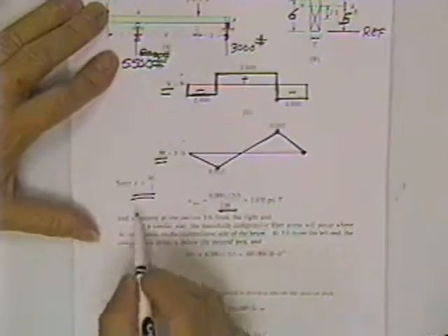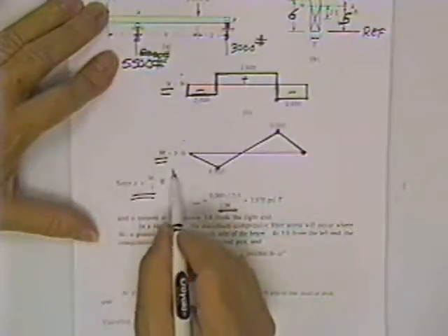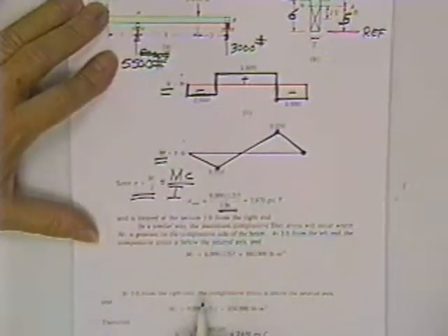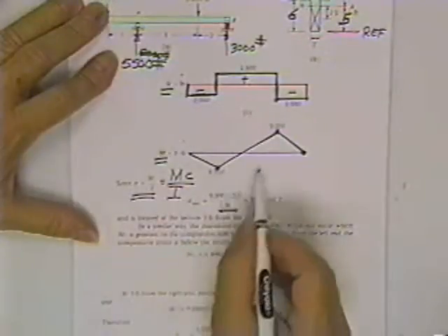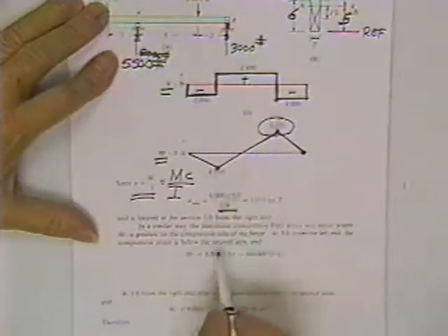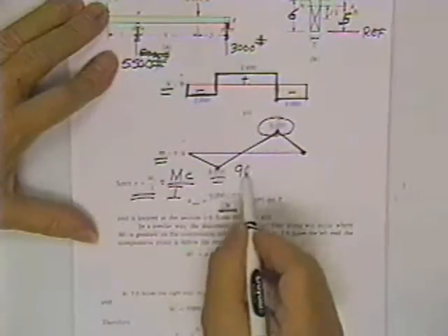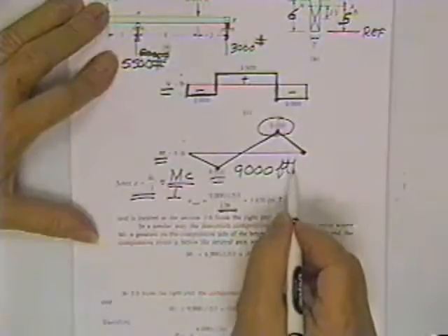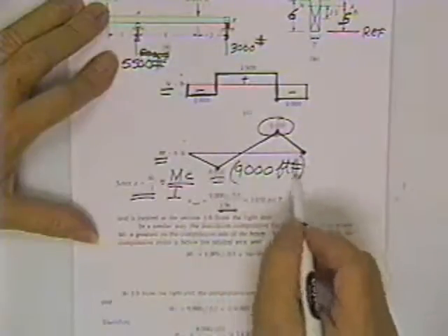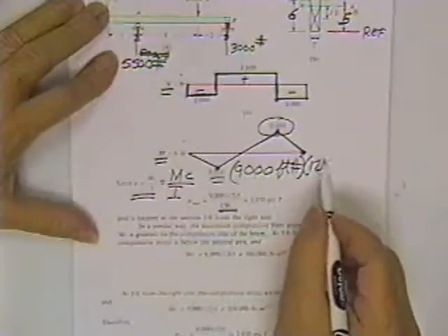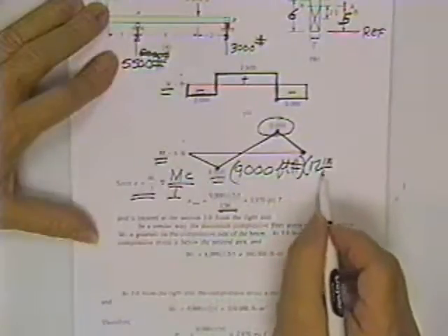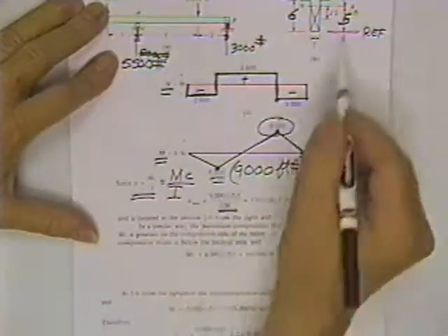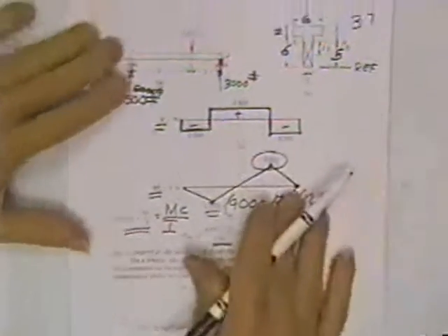The equation for bending stress is MC over I. In our case, the maximum bending moment was 9,000. In that case, it was foot-pounds. We got our moments of inertia in inches, so let's multiply that times 12 inches in a foot times C. Well, there's 2 C distances.